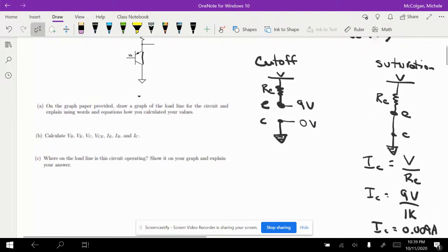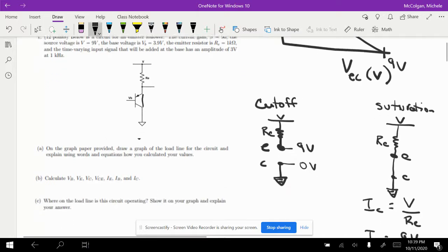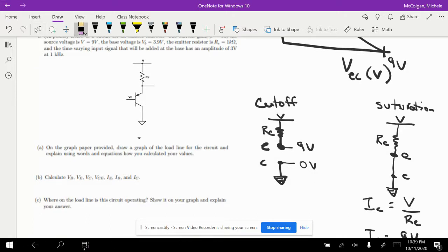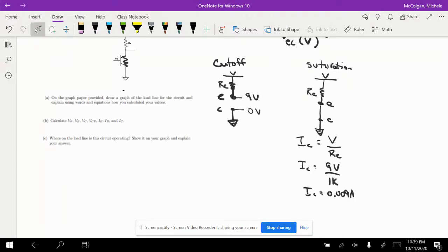Great. So now we know this is an amplifier, where this is an emitter follower, and we have this graph, and we're going to have characteristic curves, so we know this is not operating as a switch. So we know we need to do some calculations. We know for our model, we're going to be pretending that there's a resistor in here, and the resistor is going to be controlling the current that's going through the emitter to collector portion of the circuit.